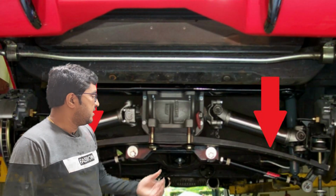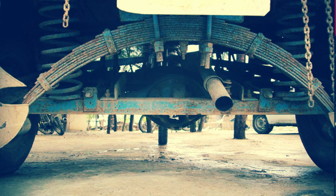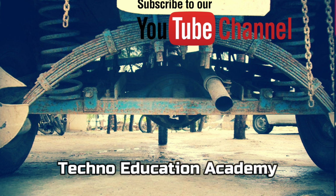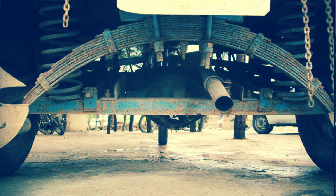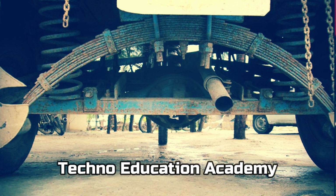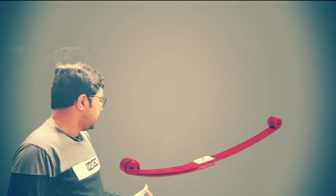The third one is the transverse leaf spring. Here you can see that in a transverse leaf spring, only the two ends are connected with the frame. The transverse leaf spring has also been used on some vehicles such as the auto rickshaw. This type is the cheapest one, but has the disadvantage that the vehicle body is attached to the spring at only two places, which gives the vehicle a tendency to roll easily when it runs fast on sharp corners.